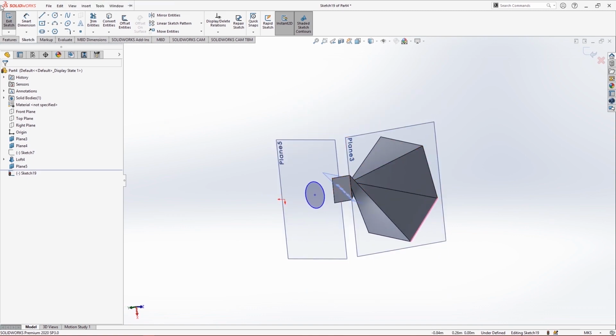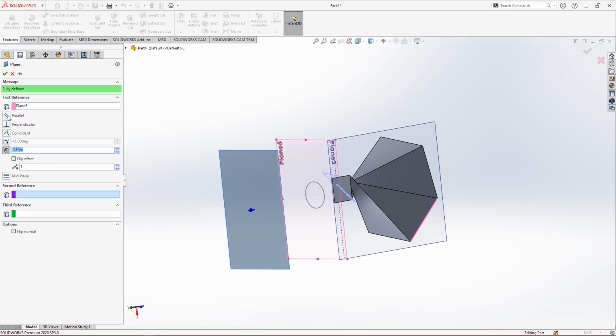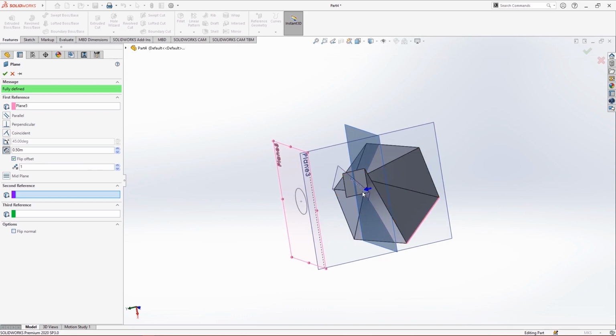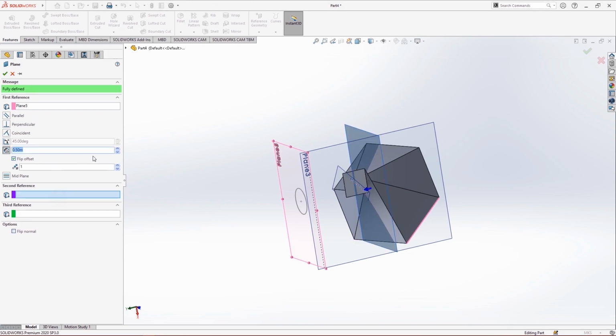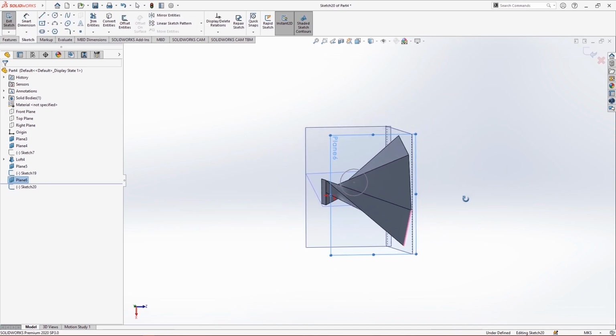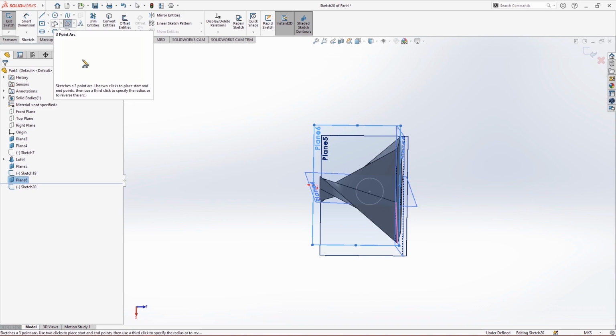And we make another surface. So we make another plane with the help of it. Flip offset means you change the direction, and yes, increase the distance. So I'm choosing sketch also on it because I need 2 sketches. So I will choose a small sketch here. Like, okay, let's make an ellipse.